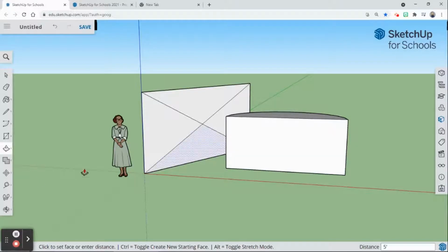You can verify those heights with your measurement tool. You can see the tape measure. There are lots of different tools here. We're going to start with this tape measure tool. If we go over here to the bottom, click on it, bring it up, and click on it, you can see that now we are at 5 feet. You also can measure the bottom. So 10 feet, 11 inches.